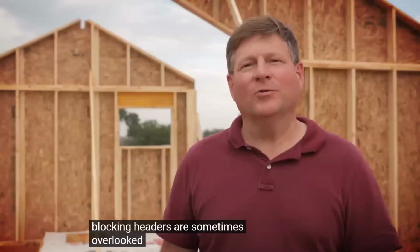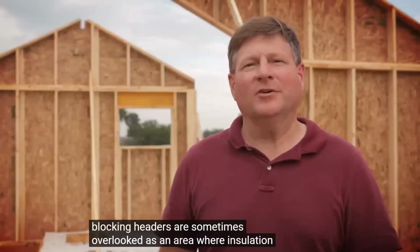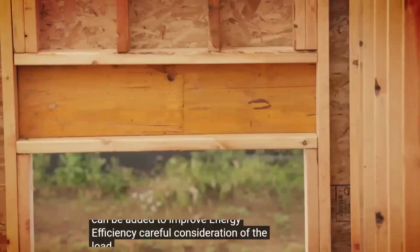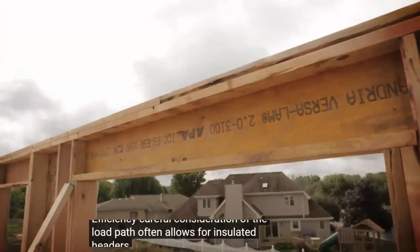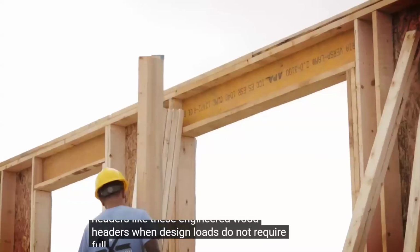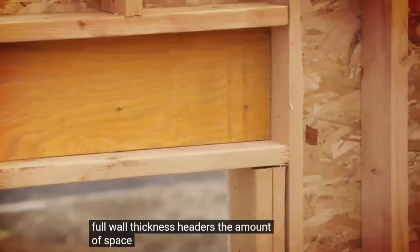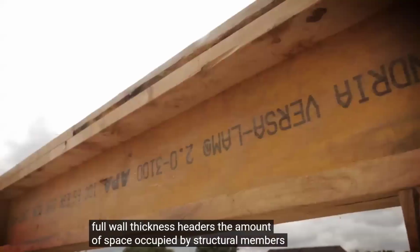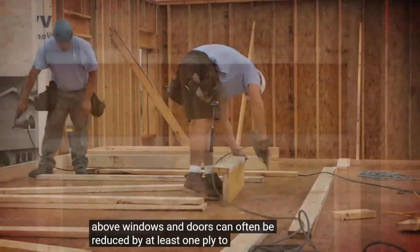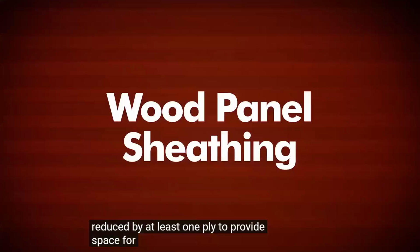Headers are sometimes overlooked as an area where insulation can be added to improve energy efficiency. Careful consideration of the load path often allows for insulated headers like these engineered wood headers. When design loads do not require full wall thickness headers, the amount of space occupied by structural members above windows and doors can often be reduced by at least one ply to provide space for insulation.